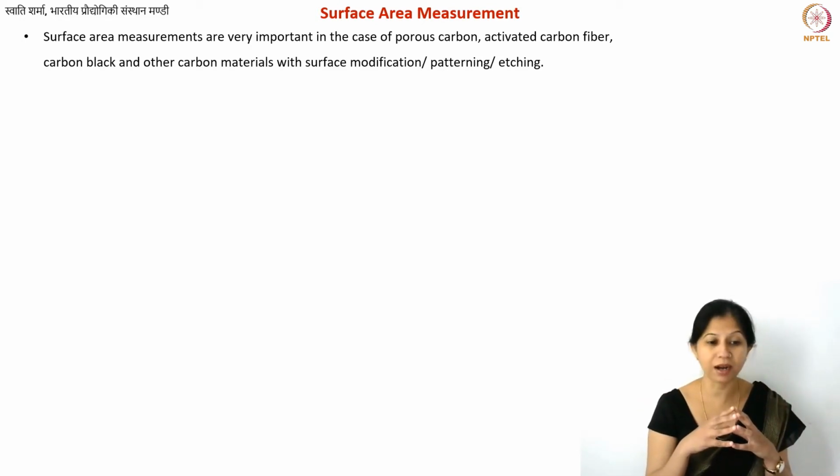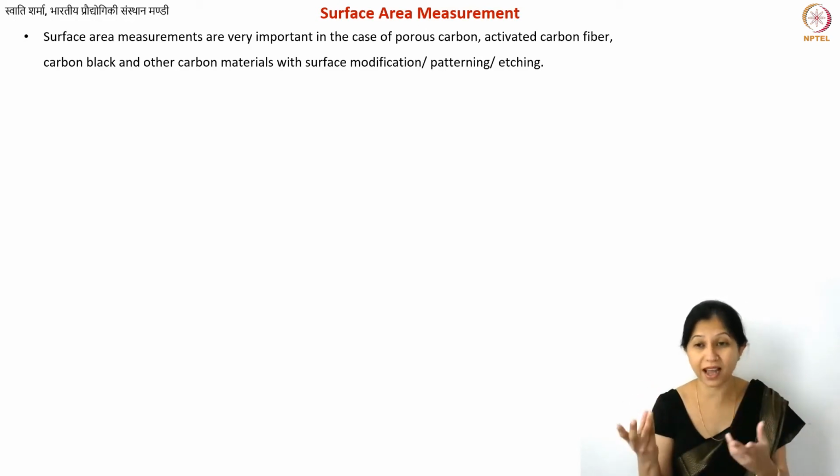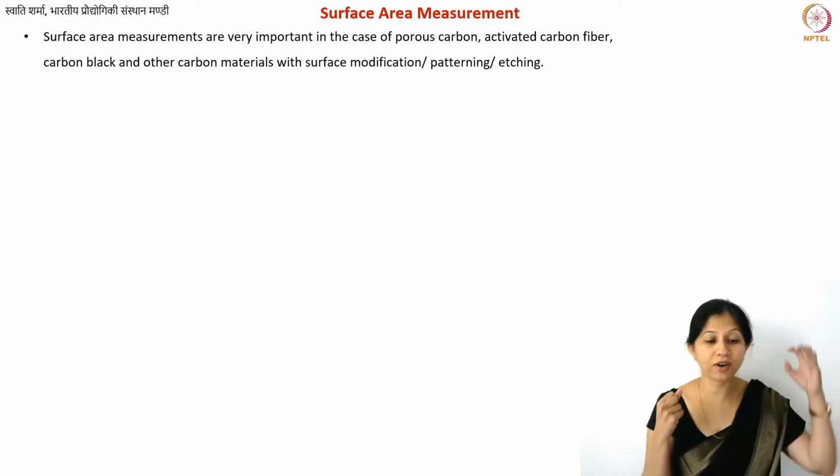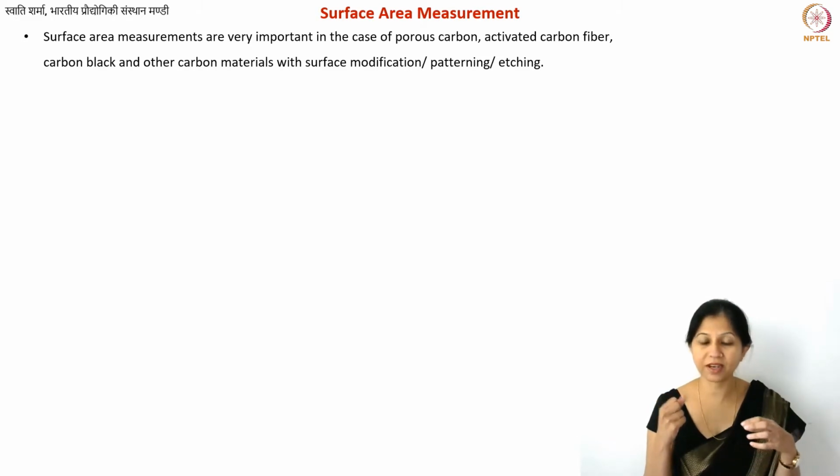By the way, surface area and porosity are very closely related. However, it's not that every time you induce porosity, you will have a surface area increase, because as the name itself suggests, it's just the area. It's a 2D thing. If you're inducing some sort of volume porosity, it will increase the surface area if and only if your pores are reachable from the surface. If your pores are closed, then it will not really reflect in your surface area measurements.